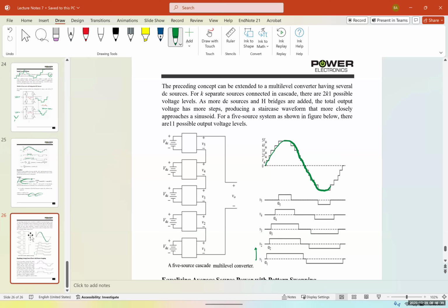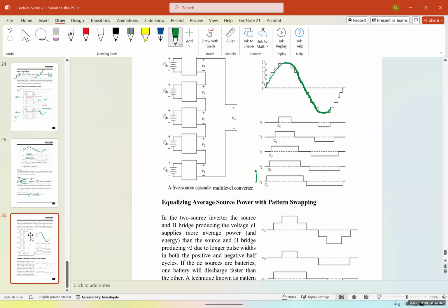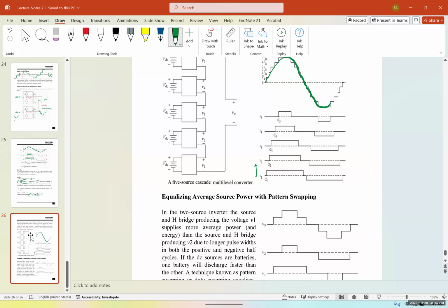Now, this is the reason these pure sine wave inverters that use this method are very expensive. Instead of having just 1 or 2 bridges, you need multiple bridges. You need multiple filters. So it's technically 10 times the material that you're going to have for a square wave. And if one of them goes wrong, the whole system is going to fail, so you need to make it durable. You need to have very big heat sinks. That's the reason that the cost is sometimes 10 times a square inverter. A square inverter is a simple switch on and off.